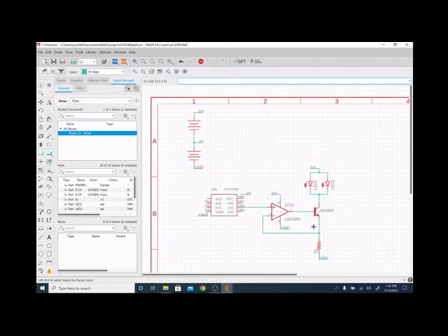The last thing I need to do is determine the value of resistor here. So if I have 3 volts at this point, because those are going to match each other when that's high, and I want 20 milliamps flowing through each one of these LEDs, that would be 20 milliamps plus 20 milliamps is 40 milliamps.